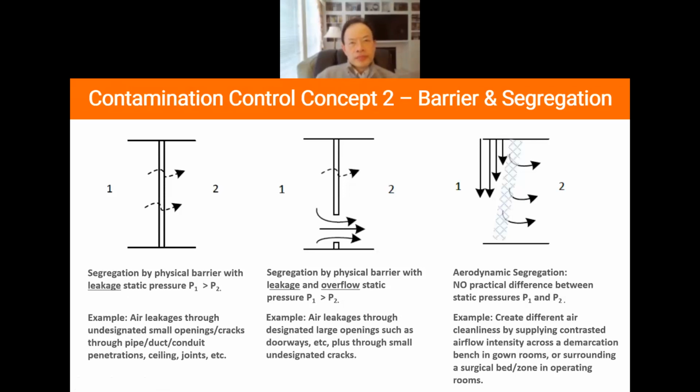There could be minor gaps in that wall, for pipe or conduit penetration. You may have caulking or seal, but it usually is not very airtight, so air can leak under certain pressure. Even with the door closed, air can still leak from the high pressure clean room to the low pressure clean room, which will cause particle migration.